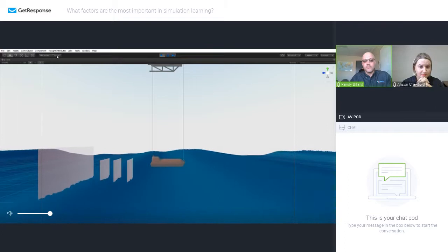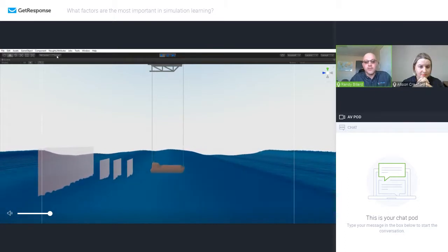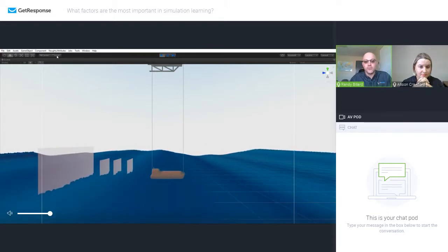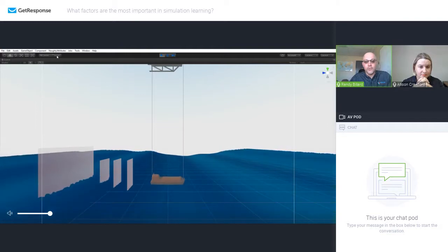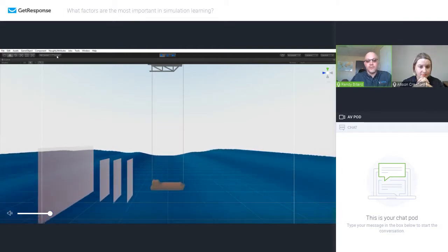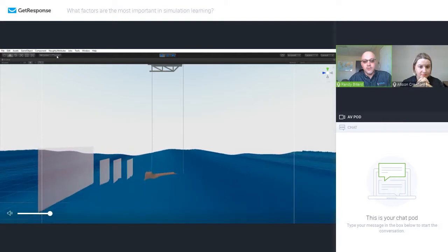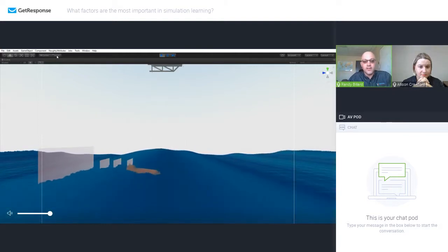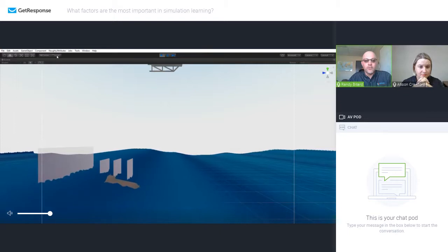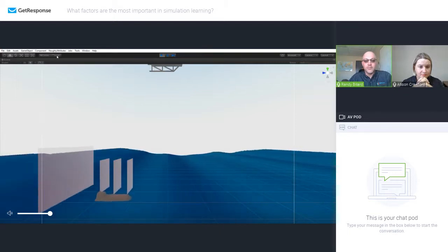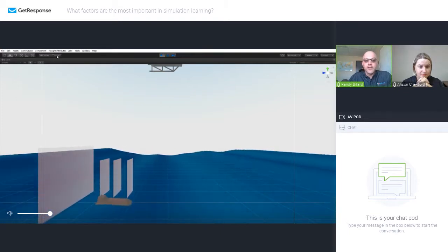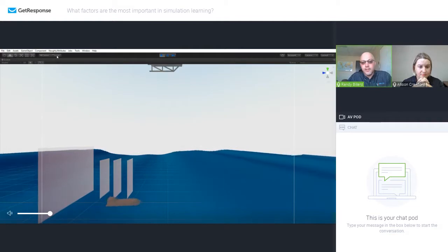So you'll see as this boat gets into the water, this is where timing becomes important. If you release your hooks, or you take too long to release your hooks, or you take too long to apply your throttle, what happens is that wave energy pushes the lifeboat backwards, and you'll see this happen in a few seconds. So the boat gets released, and that lifeboat goes back the 1.5 to 2 boat lengths, doesn't make contact with the platform, and then it's going to try and progress forward on that wave.